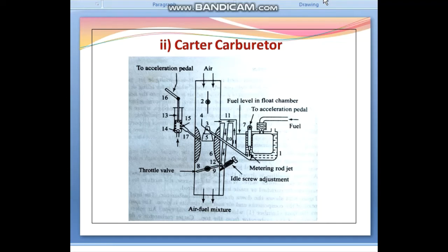The fuel air mixture enters the engine in a well mixed and atomized state, and the multiple venturi gives more homogeneous and better mixing at very low speed, resulting in steady and smooth operation at low speed. This arrangement also ensures the required quantity of mixture at high speed. The metering system employed is mechanical.